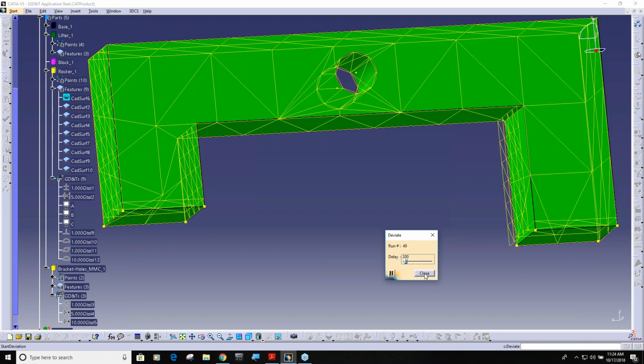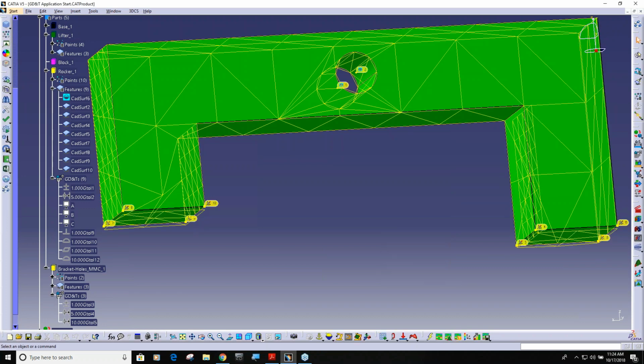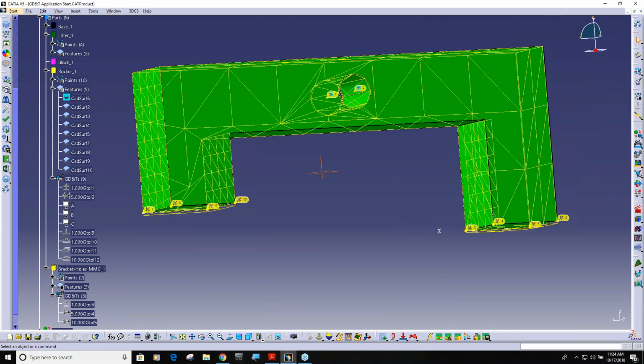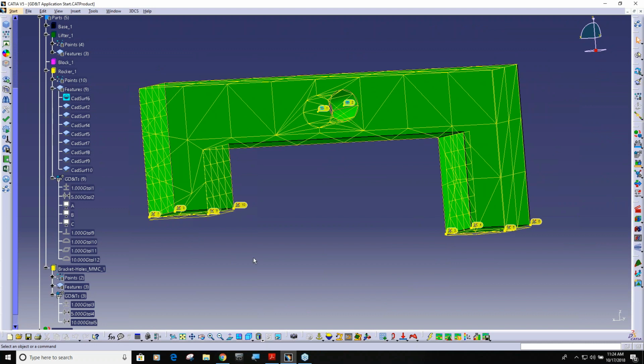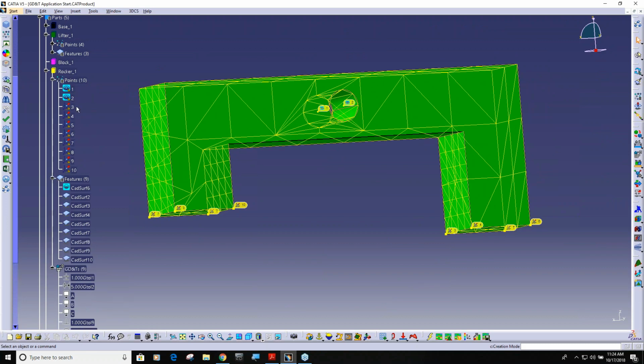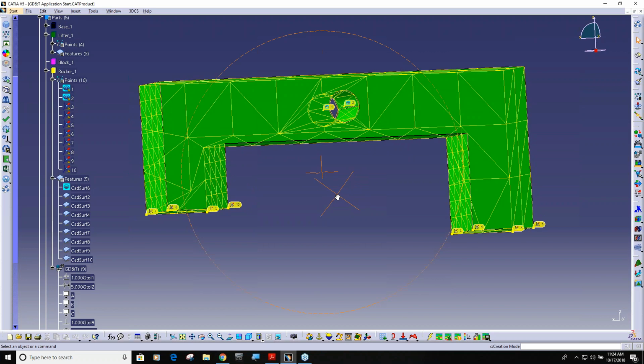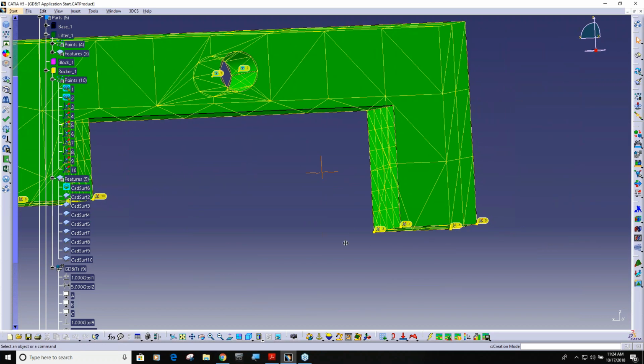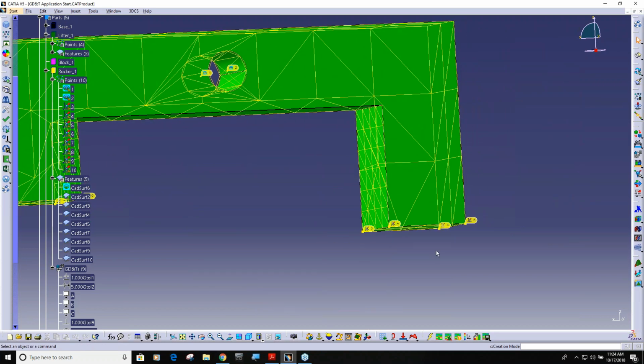Now, one of the questions that came up was, what happens if I do all point-based modeling? If you remember at the beginning of this, I pointed out that my rocker has all coordinate points. If you did your model with coordinate points, they obviously are not linked to any features. So the first thing that you can easily do would be to project these points onto that surface, with your feature point creation dialog box.